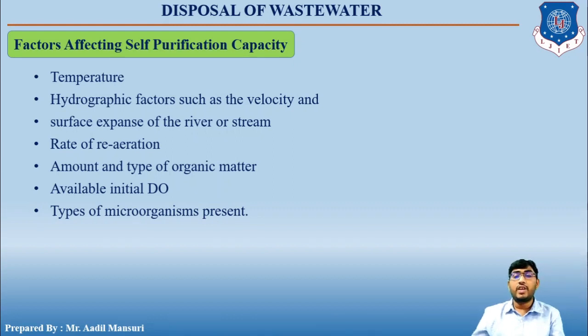The dissolved oxygen content of water, which is very essential for maintaining aquatic life and aerobic condition, is also influenced by the temperature. The solubility of oxygen decreases with the increase in temperature. So, at higher temperature, the rate of biological activity is high and the dissolved oxygen concentration is low, causing rapid depletion of dissolved oxygen. This can result in a development of anaerobic condition and subsequent odor nuisance.